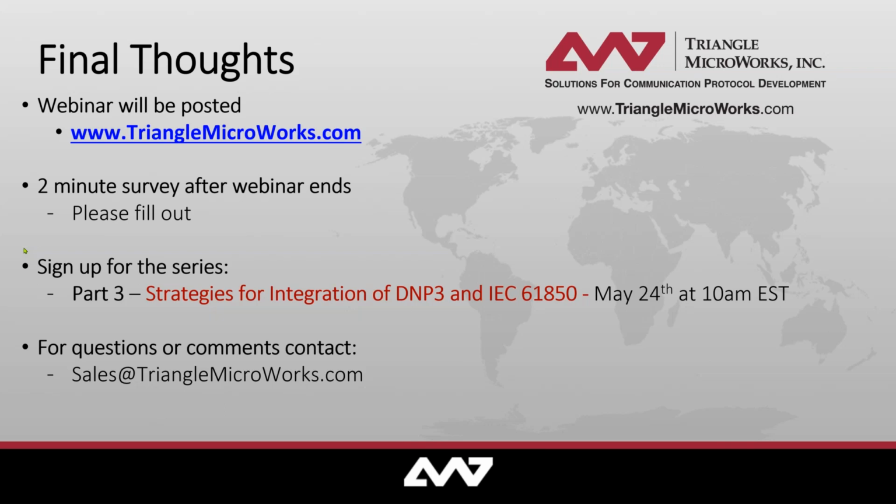Okay, so the GOOSE messaging in 61850 has some mechanisms built in that help to deal with that. As you probably know, GOOSE is sent out as a multicast. So it's more or less sent out over the network. We don't get an acknowledgement of reception from the subscribers because that would anyway not be helpful from a timing perspective.